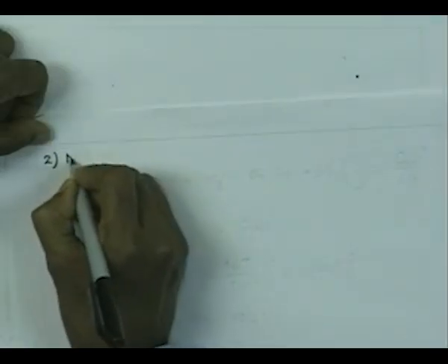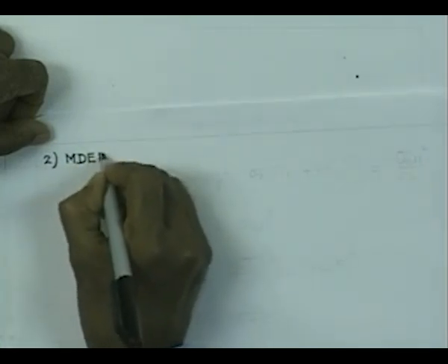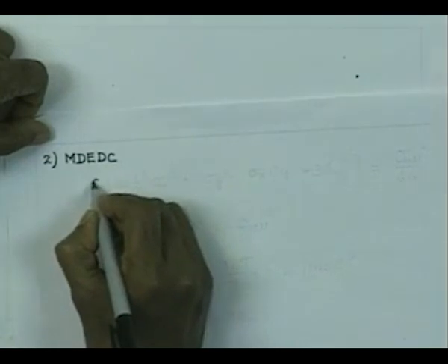We will now consider application of the distortion energy density criterion. According to the distortion energy density criterion, the distortion energy density at failure should have the value corresponding to the one at the yield point in the uniaxial tensile test. So, therefore, if we apply this criterion,